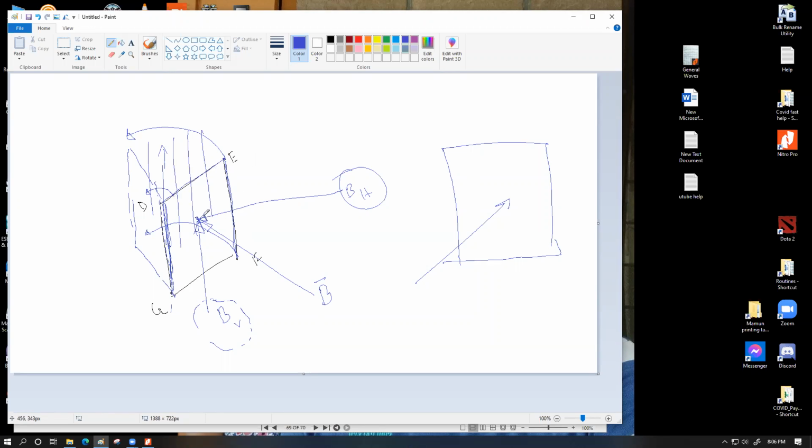Should we use the right-hand rule? No, I mean, I can find out the direction. Finding the direction might be a little difficult, but it's possible. But I'm keeping it at hand for the time being, because that's not the primary problem of this question. We can essentially find out which side would be positive and which negative by Fleming's right-hand rule, because it will be inducing EMF, but there will be equal EMF induced on either side, the DE length and the GF length. The DG line and EF line will not experience any EMF produced because of the vertical component.